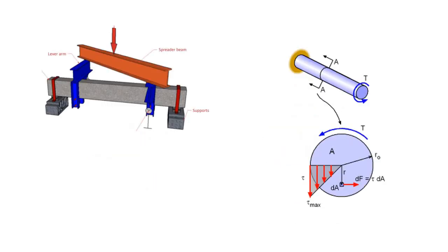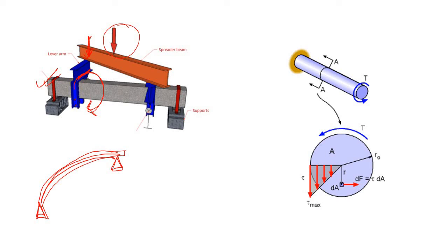Many times the beam or the girder is subjected to torsion. We have some cantilever part where there is some point load, and due to this external load a torsion is applied to this beam. The practical example of this case is the beam or the girder in bridges where they are used at a curve. In highway bridges, if there is any curve where you are using this type of girder, definitely you have to design this beam for torsion.